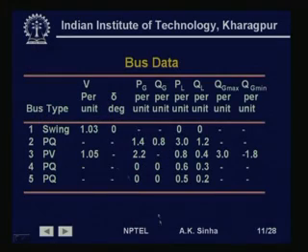So, in that case what we need to do is we will fix QG at this bus as 3.0, and then the voltage of 1.05 or whatever is the specified voltage will not be possible to maintain, and therefore, voltage will be made a variable, and this bus will be changed into a PQ bus. So, and then a load flow will have to be done again with this new value of Q fixed at this bus.